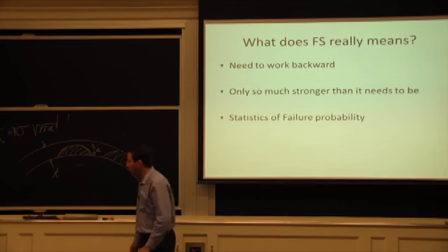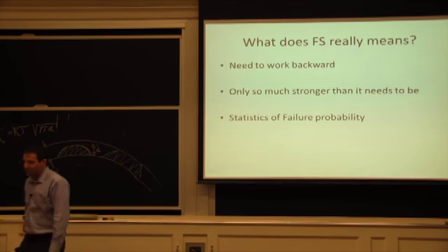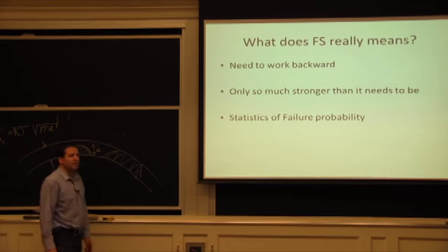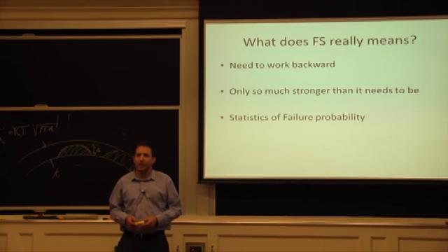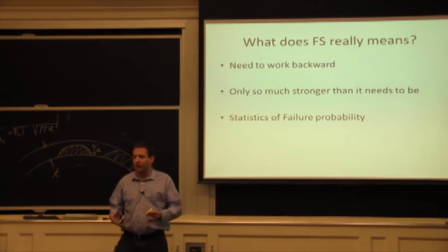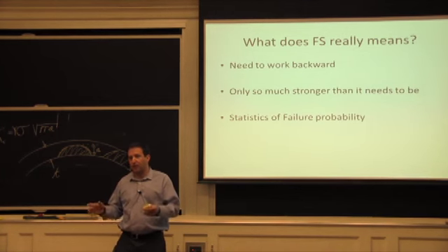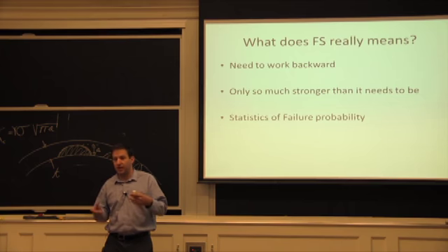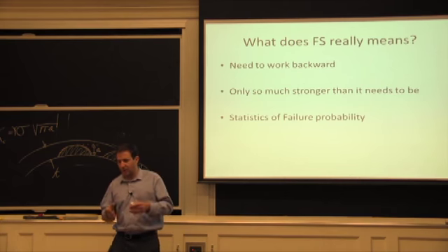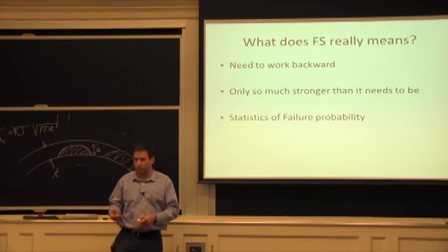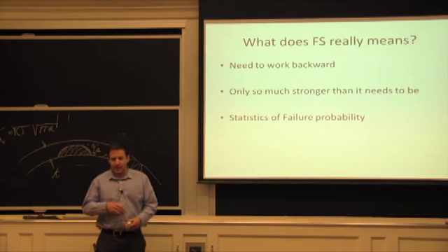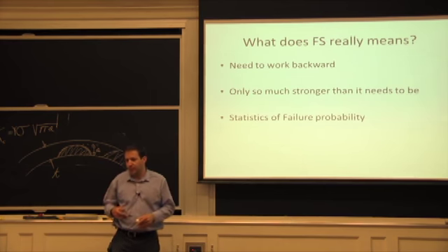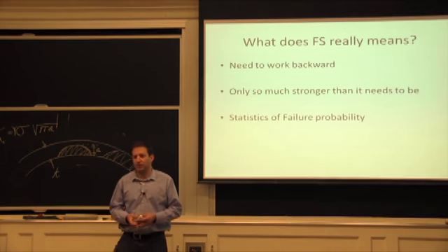If you try to come up with a new design and you want to do a statistical design, I'm sure you can. Is that going to be very helpful to you? Probably not. It would be only helpful if you look back to a similar application and find out how they consume the factor of safety by experience, how they design it very precisely, and what their failure rate is and what it is attributed to, as opposed to just saying, well, I'm going to assume that the material properties are going to be plus or minus 20% of typical value.